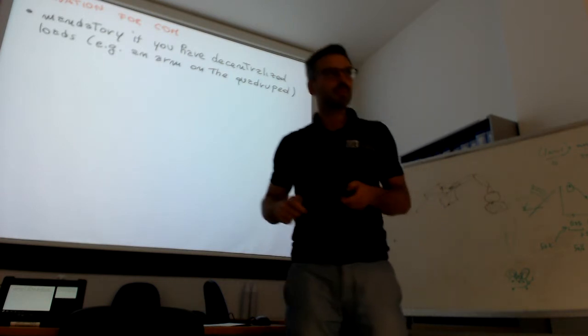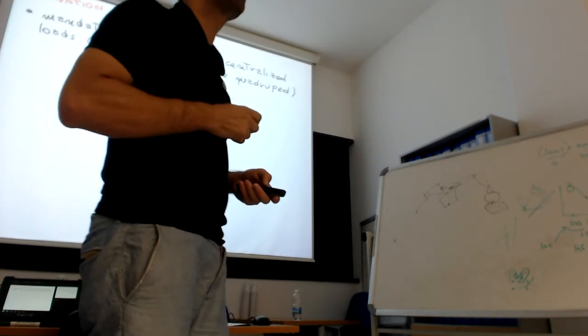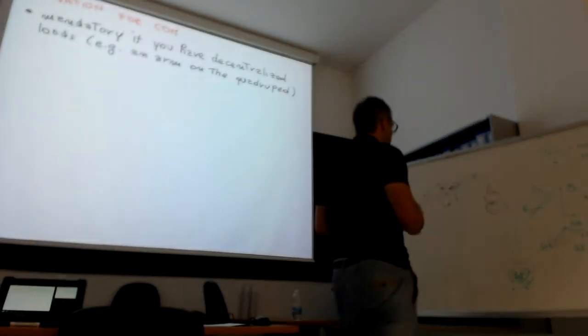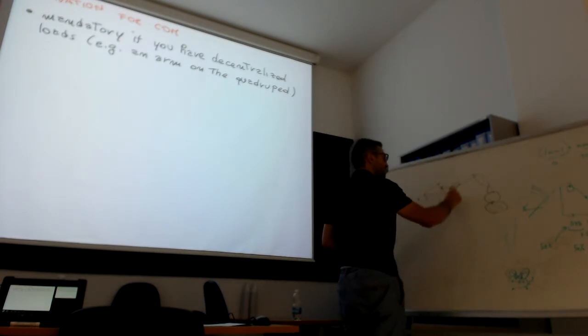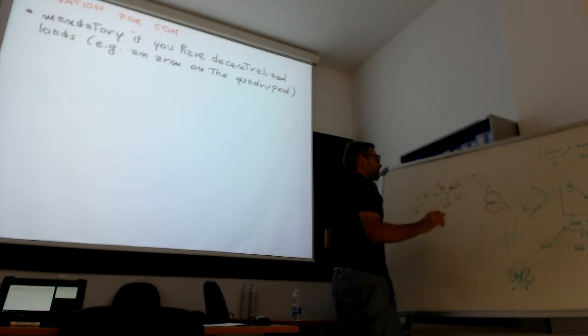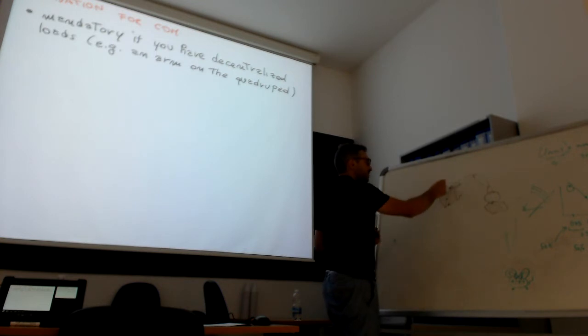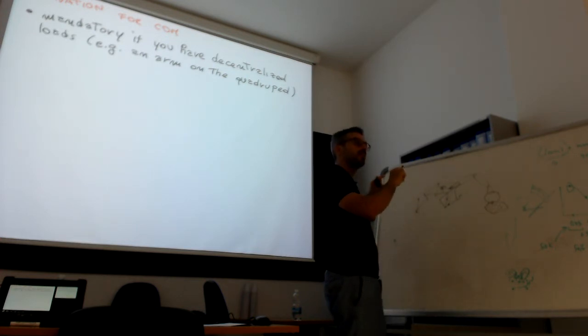How do you estimate the center of mass? Only with the parameters of the robot, or do you measure it with anything? You can use the forces. When a robot is still, there is a paper I wrote in 2017 that moves your estimation of the center of mass such that it explains the contact moments given by the forces.